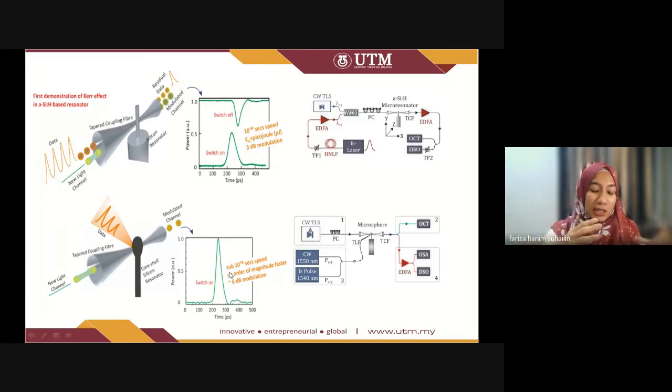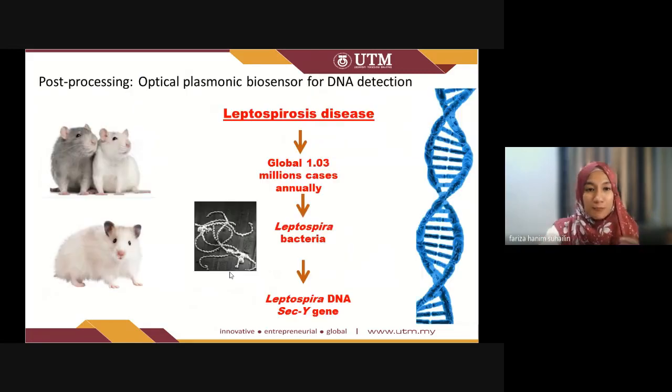at femtosecond modulation regime, sorry about that. By using all these small cavities, micron in size, you can lower the threshold for nonlinearities so that you can obtain signal processing at very low threshold at picosecond and also femtosecond modulation. This is very ultrafast signal switching, which is very promising for all-optical signal processing.